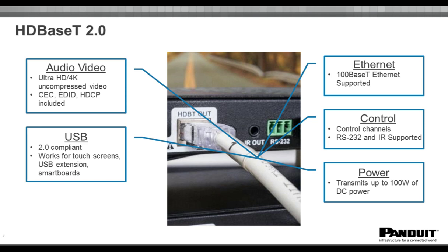A lot of people ask, what is the difference between a high-end HDBaseT device or a low-end HDBaseT device? Or why can I go on Amazon and find something called HDBaseT under $50, but then you see the high-end manufacturers charging upwards of $1,000? And the difference is actually the chips that people put on the PC board in front of the HDBaseT chip. So what you're going to see with those high-end manufacturers is they're going to put an amplifier chip, a repeater chip, and a couple other additional chips in front of that Valens chip.